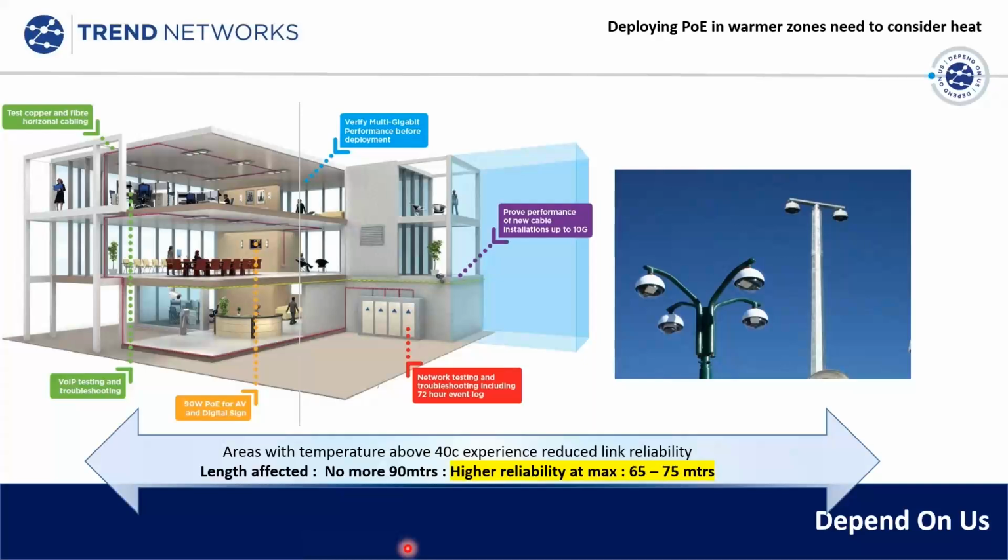So please consider temperature as a part of the design whenever you're designing these systems. If the system is already in place, please consider temperature as you do your daily maintenance routine. Is that camera on a post out there in a car park, and is it a really hot day? How far have I connected to that camera? You would need a device which can measure that length, okay? And to build in reliability or resilience, you may need to increase your power to that device.